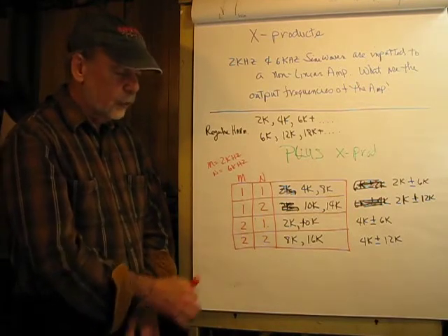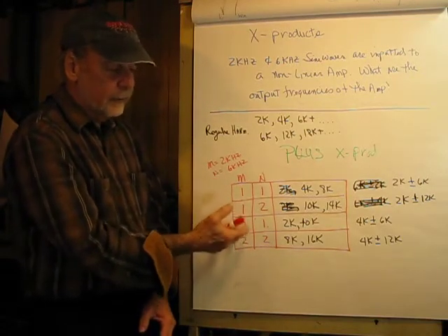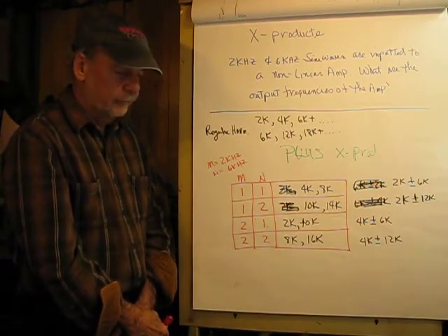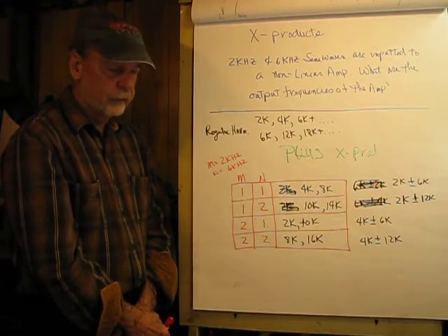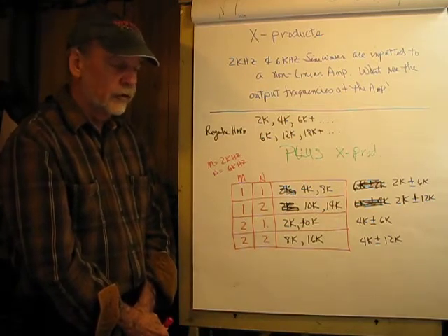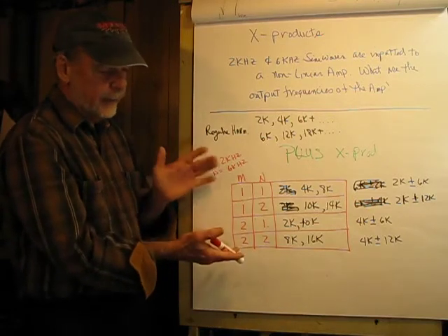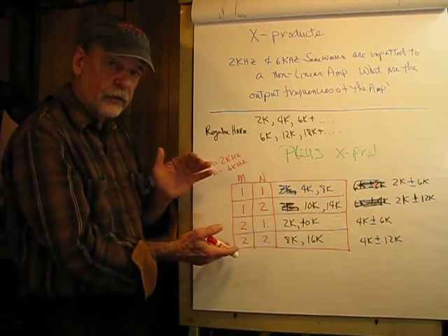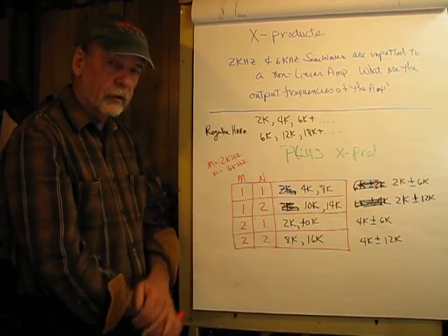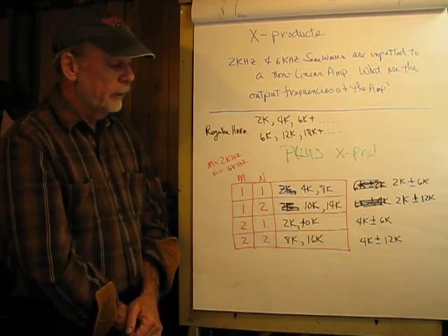So it's the difference between the local oscillator and the desired station, which is being selected, tuned, and ultimately sent to our speaker. Without cross products, we don't have a radio. The diode detector that I mentioned is very nonlinear also, and that deals with cross products to get from, say, a frequency of 455 kilohertz down to audio baseband stuff we can hear, all based on cross products. So that's about it for cross products and distortion, and thank you for watching.